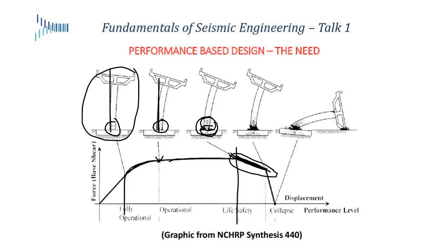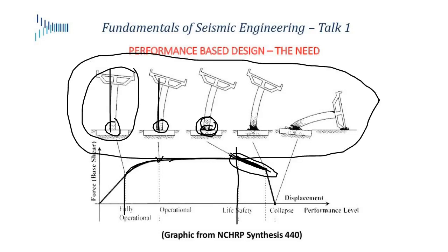So with performance-based design, the moral of the story is that we can actually figure out this whole range of structural performance. We can define where my structure is going to be sitting. So I could say after an earthquake, I'm going to be sitting somewhere here, so really I don't need to do anything, or I'm going to be sitting somewhere here, and now I need to have some intervention happening.